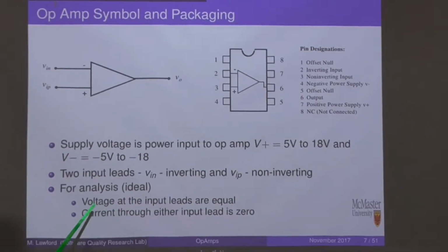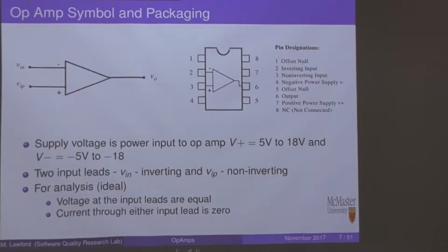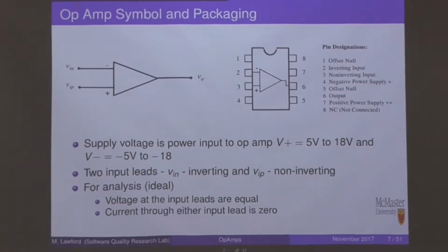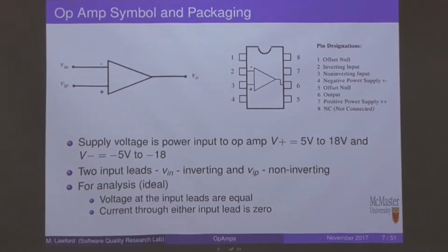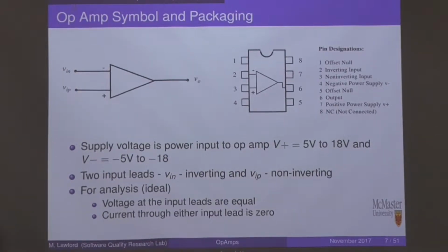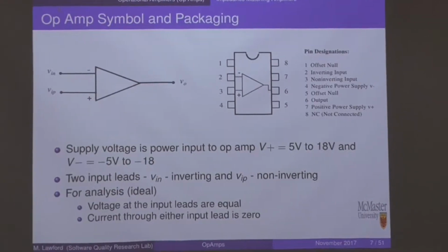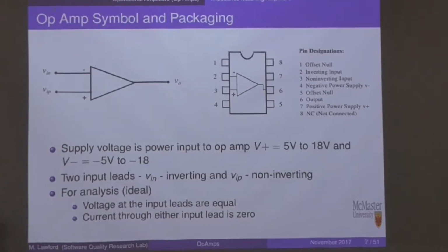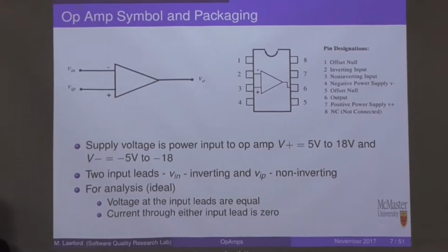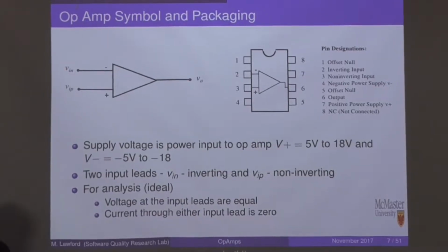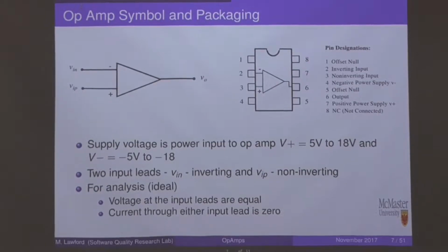These are approximations which assume that the operational amplifier works precisely and exactly as it's intended, with no additional complicating factors, which of course can't possibly be the case. As we're going to see over the course of this lecture and next, operational amplifiers do not follow these laws perfectly, but this is sort of the intent, and normally they operate well enough that you can hold these two laws to be true for the purposes of circuit analysis.